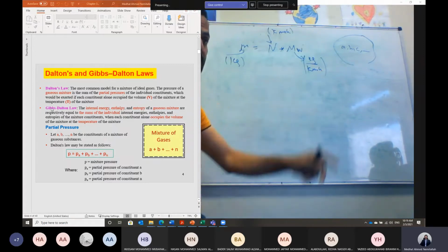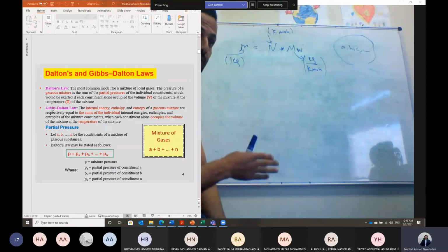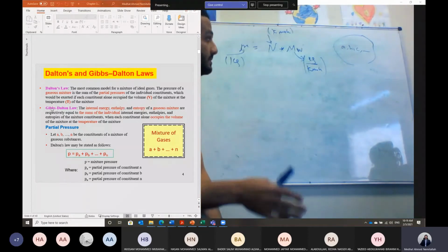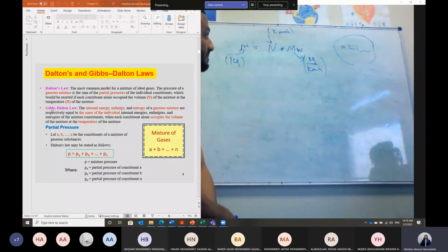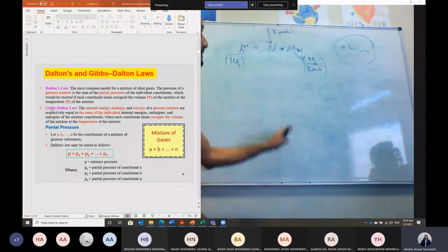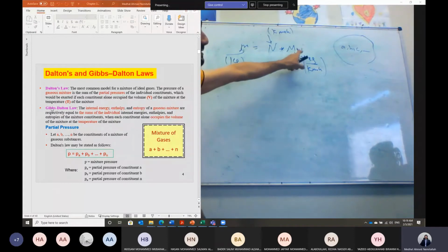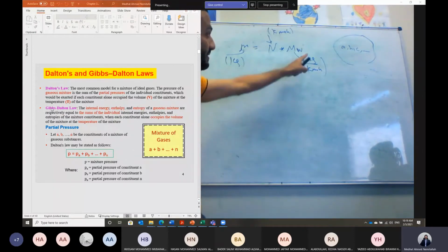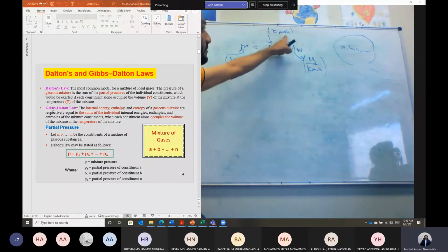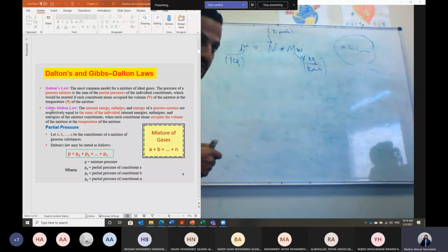You will find the properties like the gas constant R and the molecular weight, specific heat for different gases. I have just uploaded for you some tables on the blackboard. This is actually part of the book on the internal combustion engine that I'm preparing right now. You will find the molecular weight is defined in kilogram per kilomole, and the number of moles is calculated in kilomole, and the mass is calculated in kilogram in this case.